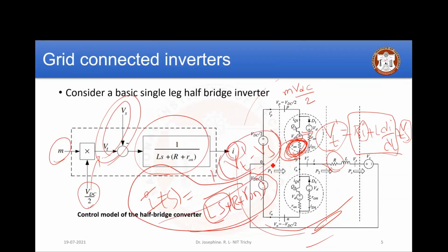What I have control over here is the modulation index M, for sinusoidal now. Whatever we are giving, suppose it is a sine function, we are giving two inputs: one is theta, one is M. I already told you at the time of PWM techniques, by controlling M, whatever the sinusoidal signal you are comparing with this repeating sequence, your output voltage is going to change correspondingly, and your current also will change.